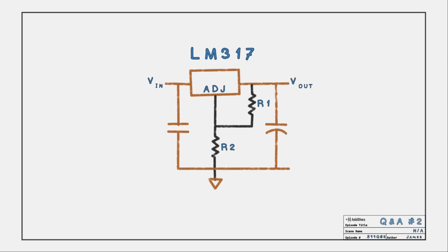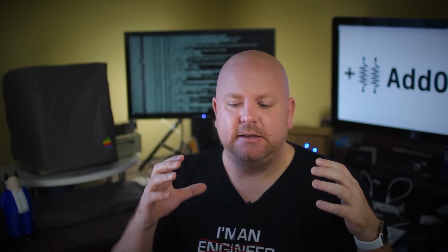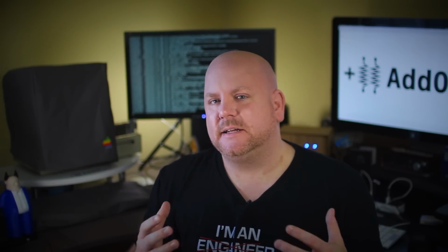And so you could use 2 fixed resistors to select any voltage, or sometimes what you'll see is a potentiometer so that you can actually adjust the output voltage. The really cool thing is the fixed regulators actually sort of already have that circuit built in. Not only that, you can also use a fixed regulator as an adjustable regulator, sort of. And we might cover that later on because I think that's a good way to understand how linear regulators work.